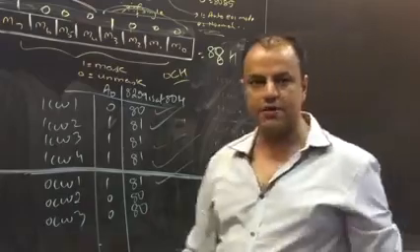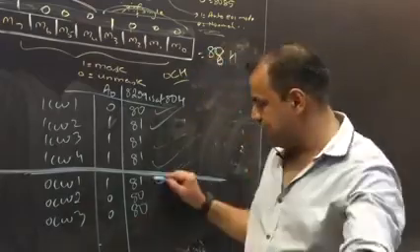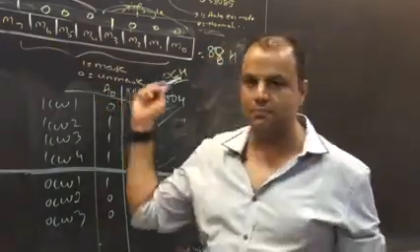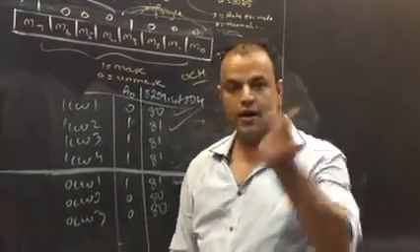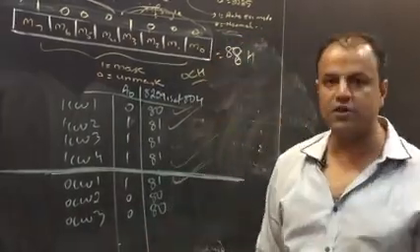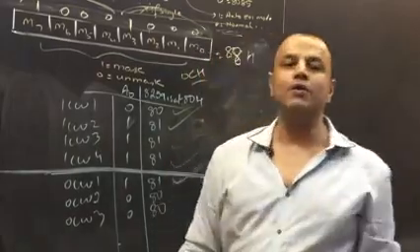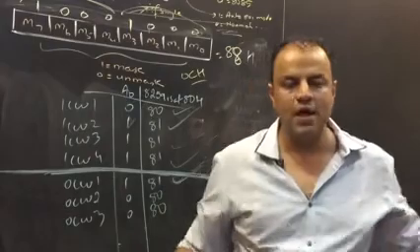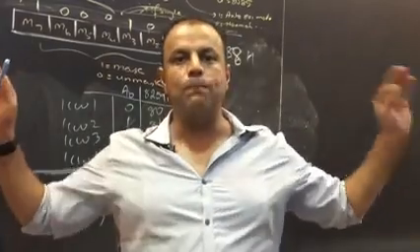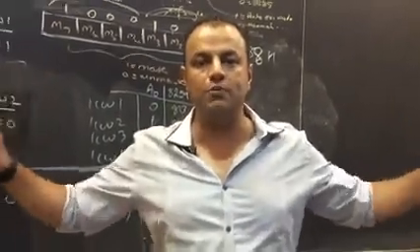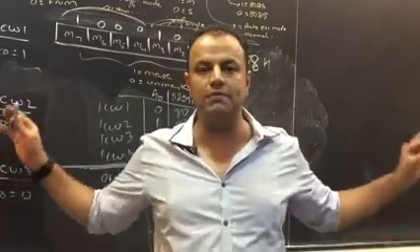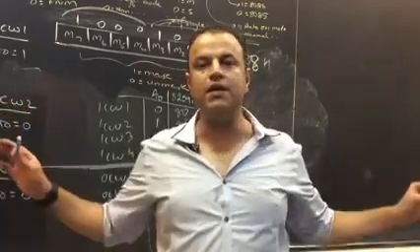Yes. After 10 minutes, I give you OCW1 again. Yes. Again. Yes. Why am I giving again and again? Masking. I can keep changing the masking pattern. Every time I give you OCW1, you will know it is OCW1 because the other 3 commands which could have come at the address 81 cannot come again. Are you clear? So that means from now onwards, the address 81 is booked. 81 is for OCW1. Anything coming at 81 blindly will be treated as OCW1. Are we clear on this?